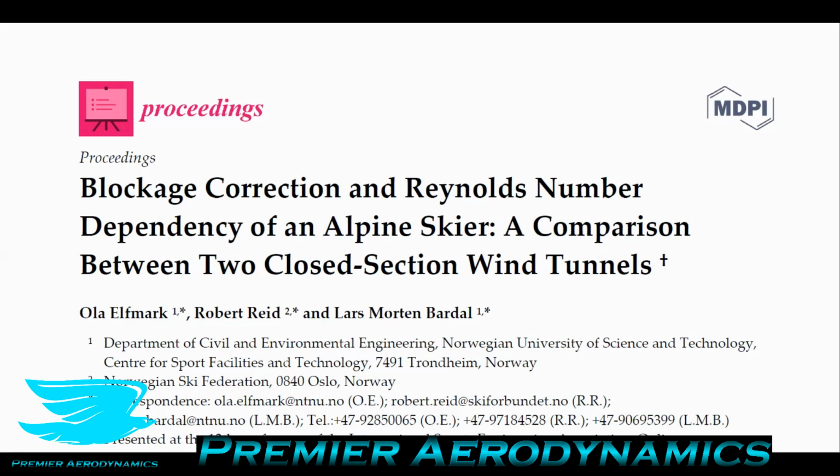Now, obviously in wind tunnels, the reduction in area is not that great. Usually it's maybe 5% or 10%. So it's not that dramatic, but it still does have an effect on the speed of the flow going past the object. If the flow is faster, you're going to have a greater Reynolds number, and that has localized effects. And that's what we're talking about today and how to correct for them.